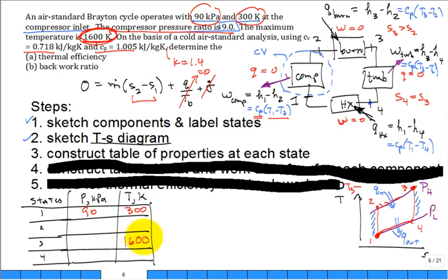1600 Kelvin. So those were the easy ones. Now we have to do a little bit of work, but the pressure is easiest. You can probably get all of those 3 remaining pressures with just a little observation here and there. So, how about the pressure at 4 compared to the pressure at 1? Same. So, I color code that blue. You had to use a little logic. You had to know, hey, the pressure between 1 and 4 is the same.